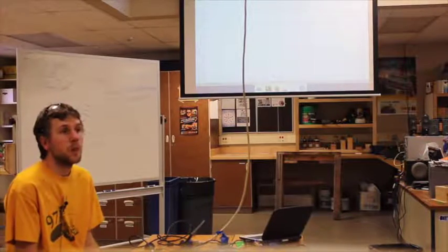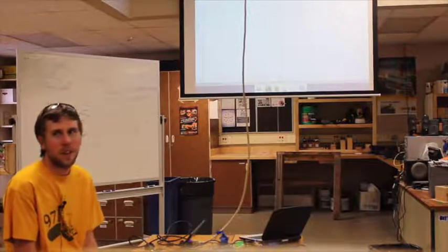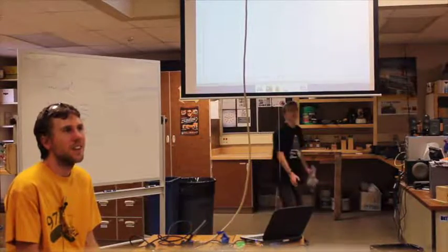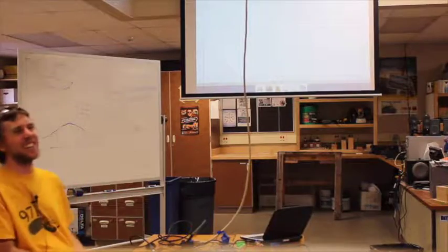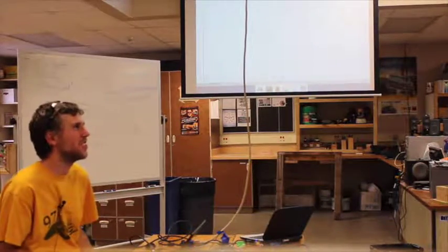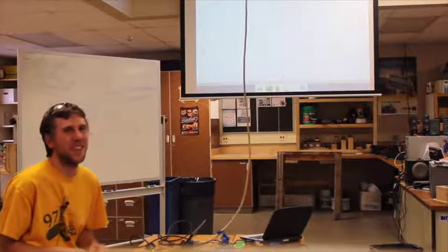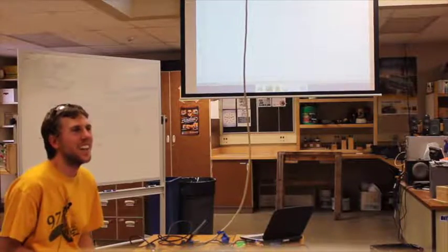Another thing is, if we don't know where we are yet, because we're not zeroed, should we be allowing full 12 volts to our motor? Very good. So we should add a feature. Actually, the first thing we should do is we should write a test to verify that it doesn't work right now. Then we should fix it.